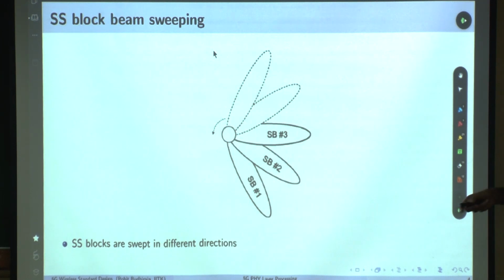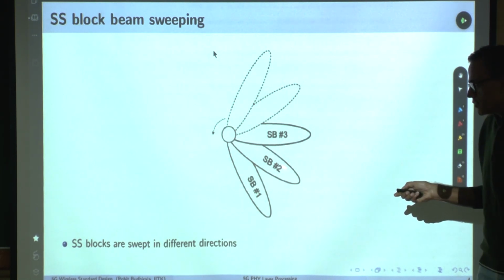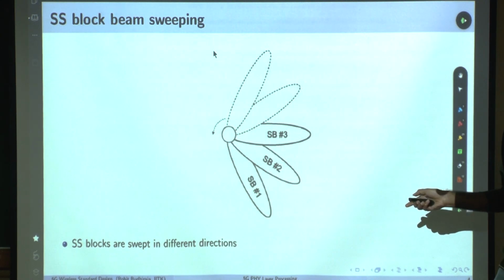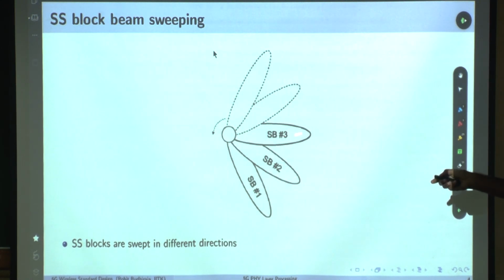So, keeping this in mind, the base station retransmits this synchronization block, with certain changes which are specific to this beam, in this direction, and then in this direction, and keeps doing that. So a user located here, as I showed you in the last slide, will be able to synchronize to this beam. And the base station has to continuously keep doing that.